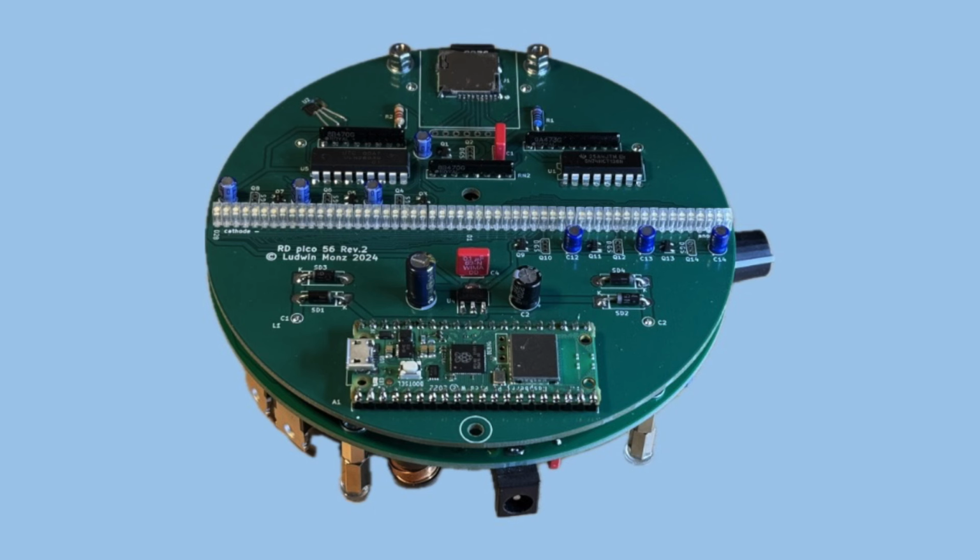The display is a 4-layer board. The 2 inner layers are used as grounding planes. This is necessary to minimize interferences from the fast current pulses. All other boards have only 2 layers. So much about the